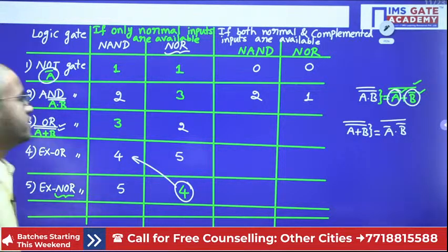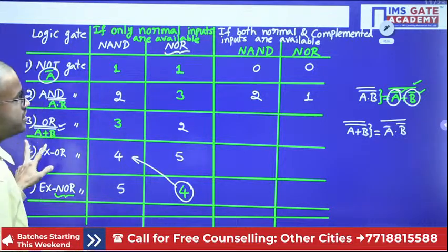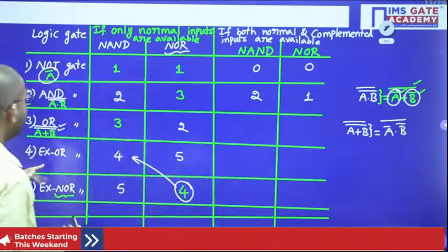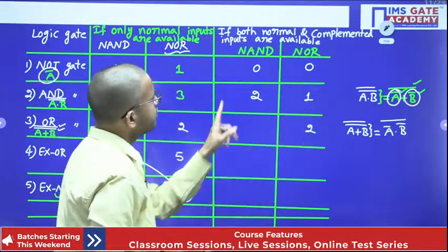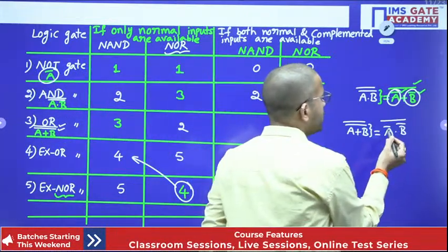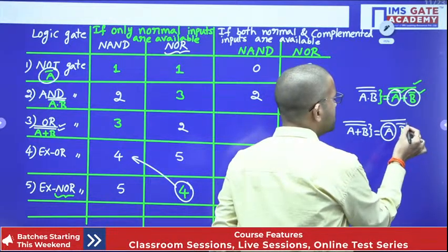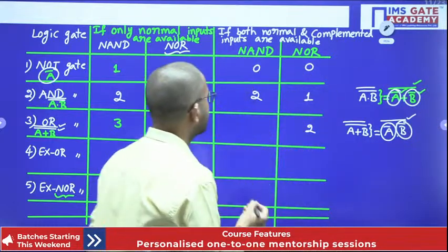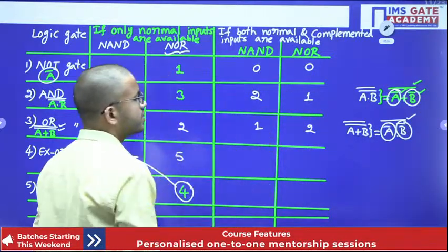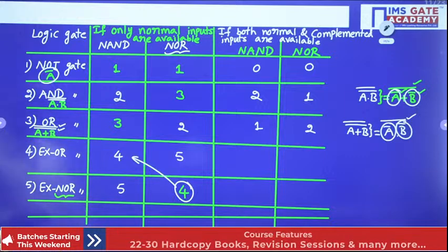Yes, very good. So regarding OR gate, first of all, if you consider with the help of NOR, obviously we require 2. And if you want to implement with the help of NAND, here A bar is available, B bar is available. So these two outputs you are passing through a NAND gate, that's all. So that means 1 and 2, right?